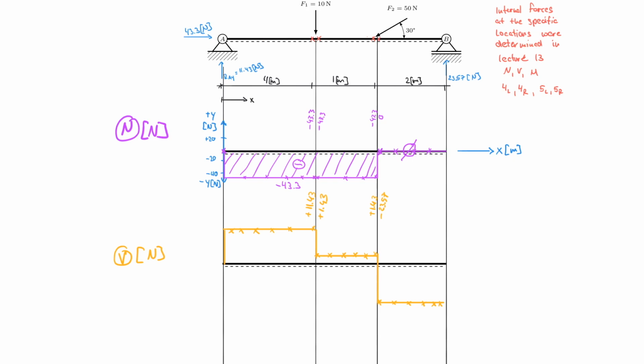And if you don't believe that right now, you will definitely believe it once you have some practice with these problems. Now it's a closed shear force diagram, which I complete by marking my plus and my plus here and my negative. I have to indicate this. Students always ask me, is this really necessary? Is it a waste of time to actually shade the area? No, it's not a waste of time, because these graphs will become more complicated as time goes on, and then you have to clearly identify that you understand where something is positive and where something is negative.